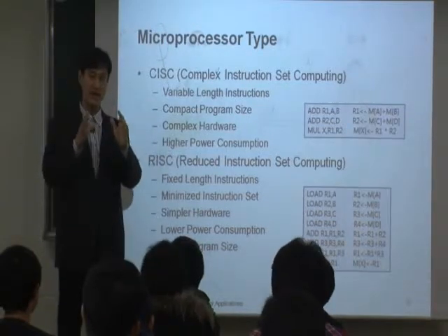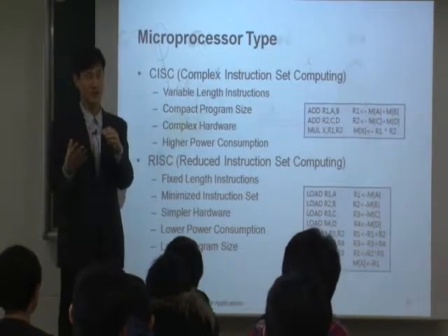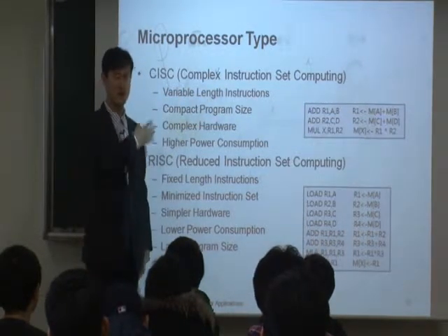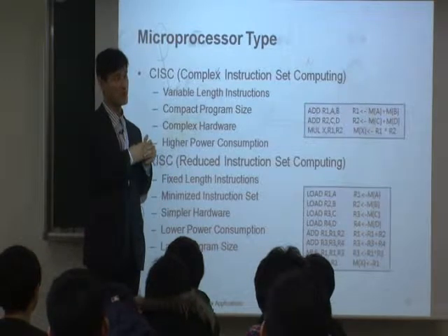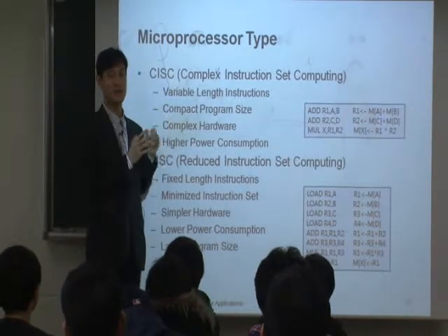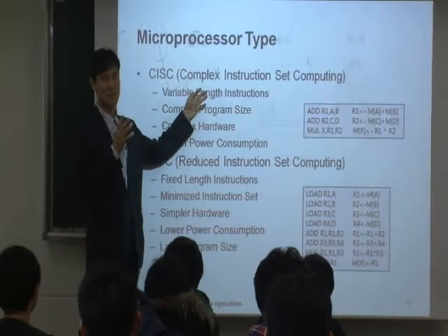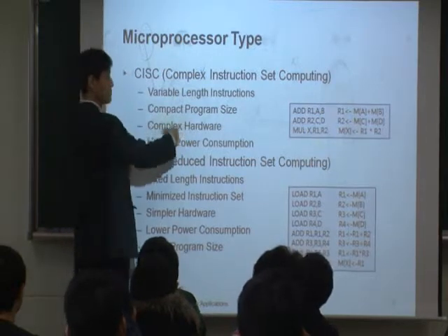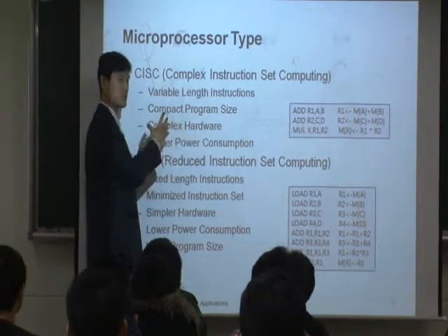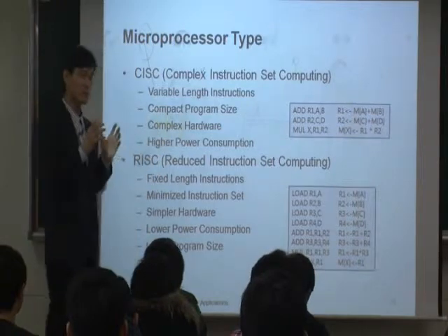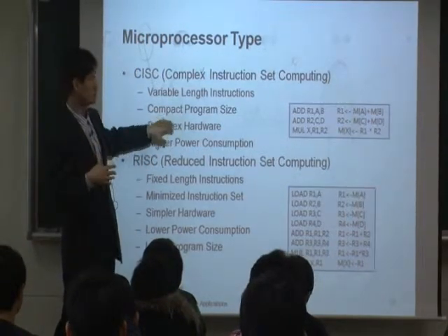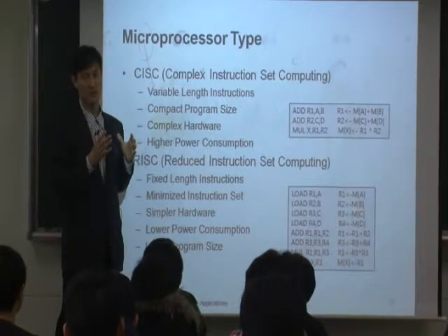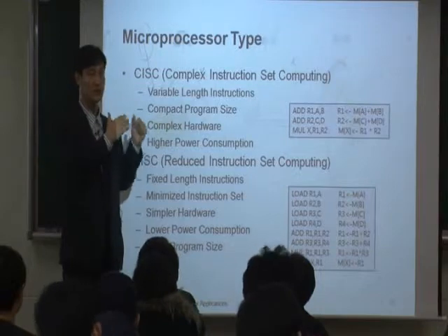So basic ones, like add and subtraction, you always use. But some of the very complex instructions, maybe you use them like once a day or something. It's very rare. Okay? You are not using it all the time. But since you have everything in here, you have a very big hardware, okay, and large power consumption. And another big problem is that in hardware, generally if you have a big hardware, you cannot increase the clock speed. Okay? There is a certain limit on the clock speed.